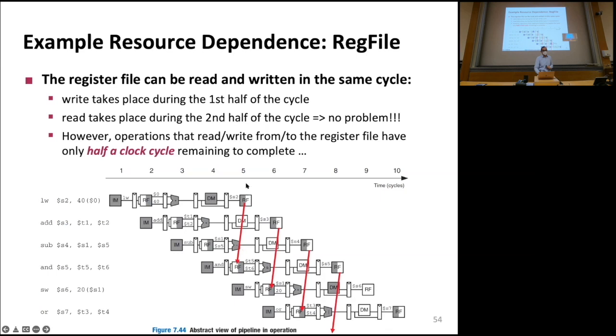We're going to eliminate some issues with data dependence by enabling the register file to be written in half of the cycle and read in the other half of the clock cycle. Does that make sense? If you didn't do that, then you can basically say this register file write takes a full clock cycle and the value is available in the next cycle. Clearly, this will reduce your performance a little bit. Here, we're making the value available in the middle of the cycle so that someone else can be in the same stage and read it in the same clock cycle, right? That's the idea. That's the benefit of this.